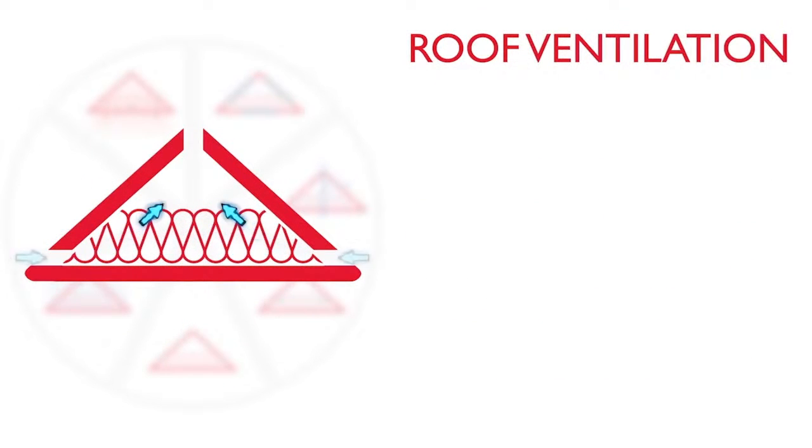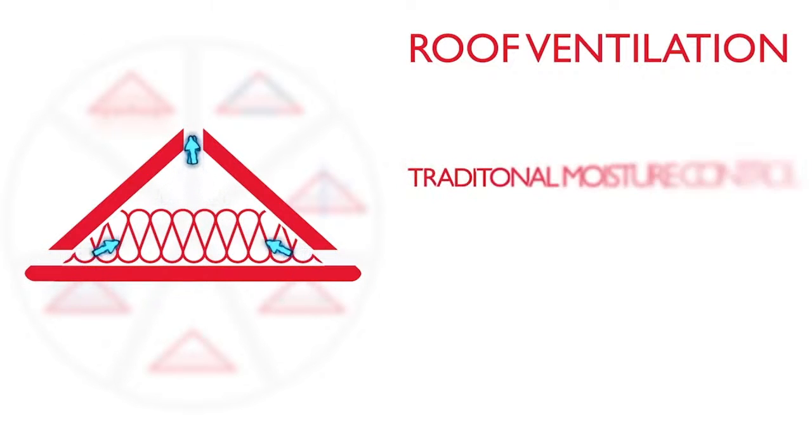Roof ventilation. Finally, we must consider the ventilation provided in the roof, or not. Whether or not roofs and lofts require ventilation has been the subject of a long-running but now largely settled debate across the industry since vapour-permeable underlays first gained mainstream acceptance in the 1990s. Traditionally, roofs of all kinds required ventilation to ensure moisture could escape, as bitumen felt underlays did not allow moisture transfer to any significant extent.